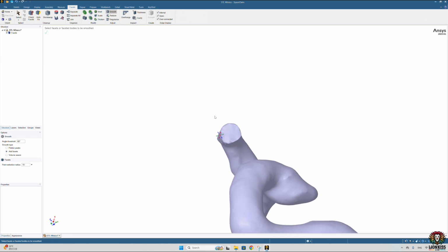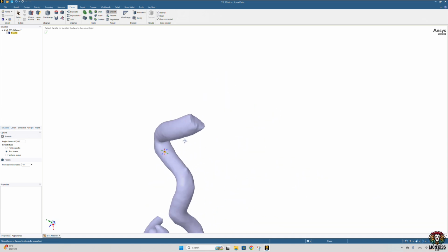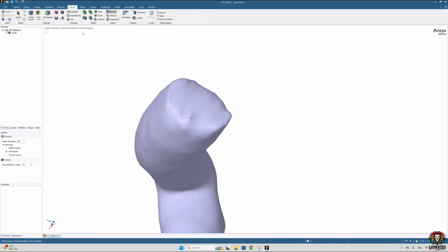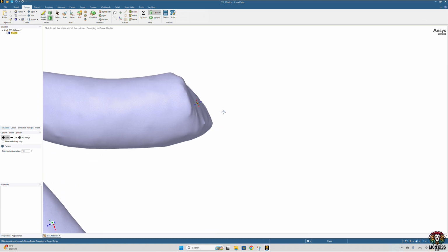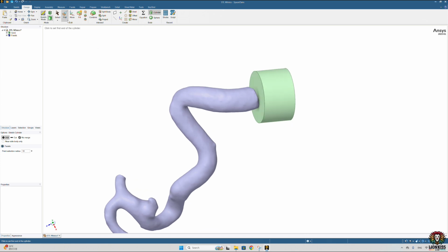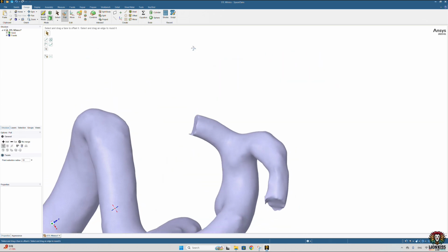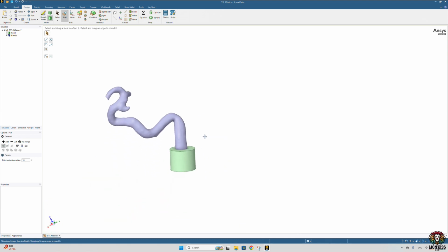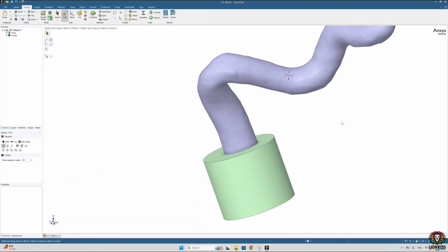Yeah, now it's time to make the outlet and inlet smooth because they are irregular. So for that we go into the design and select the cylinder and click on the center and make one line and make one tube. As big a tube as is good, and moving to the pull and select the pull, and we can see whether it's cutting the proper plane or not, it should be a smooth cutting.